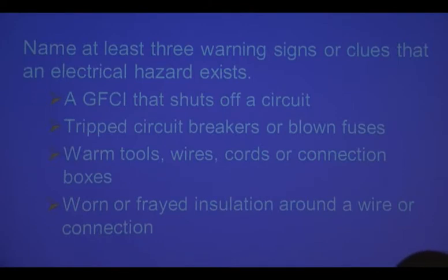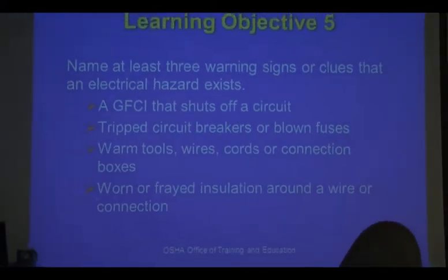If the thing is warm, it might be your drill from using it, and there might be a reason for it to be warm. It might have been used for 30 minutes straight, and it's not designed for that. But still, if it's too warm, if it's warm at all, there's a reason why it's warm. So you need to investigate.